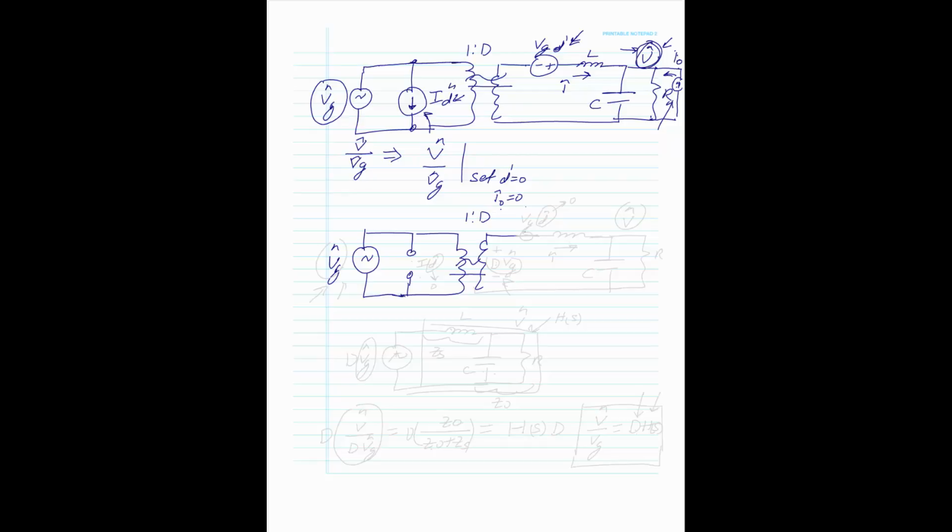And what do we have here? This circuit here is a short. That is VGD hat, because we're setting this to 0. Just like we set ID hat and we set this one to be 0. That's an open. The current source is an open, the voltage source is a short. We put back the inductor. We see that's I hat. And we put that to voltage V hat.